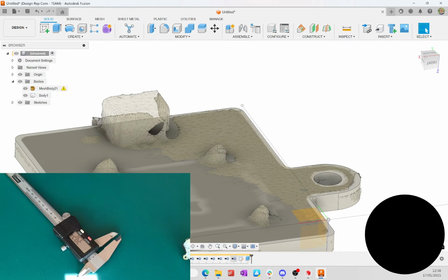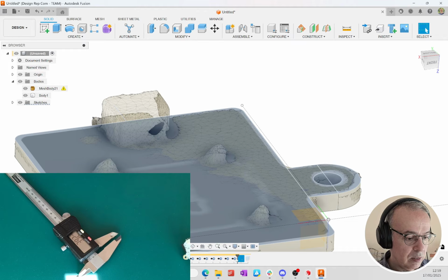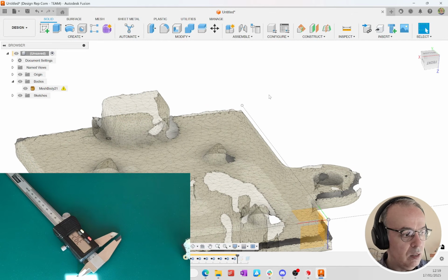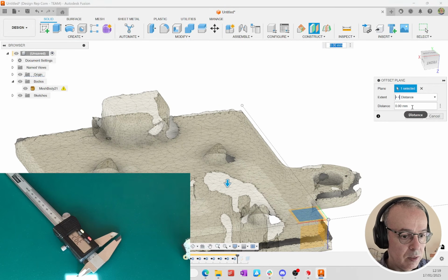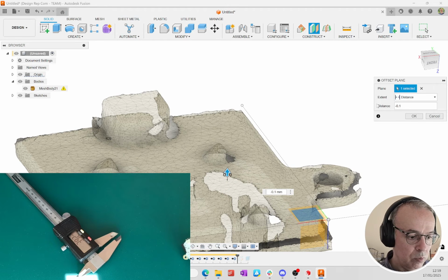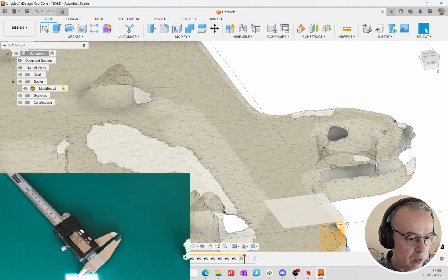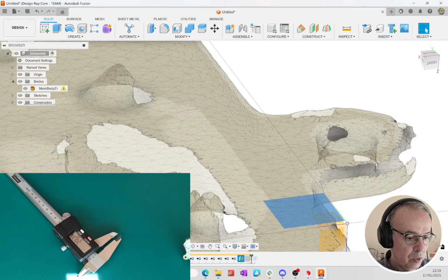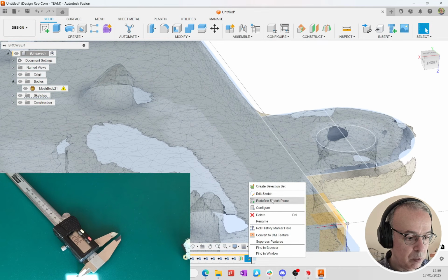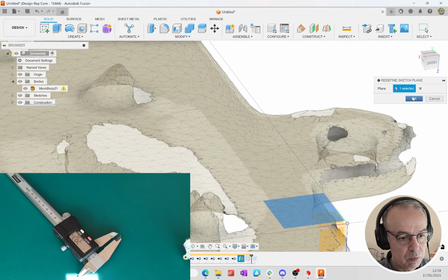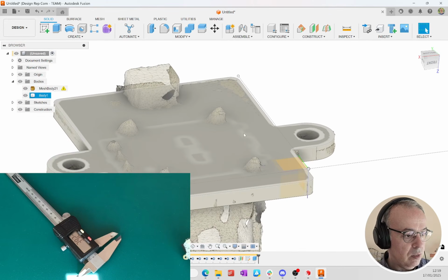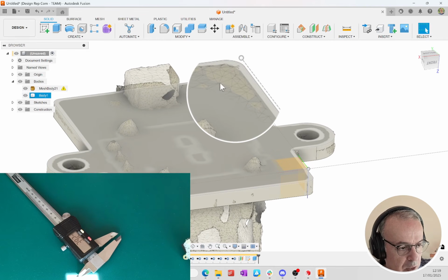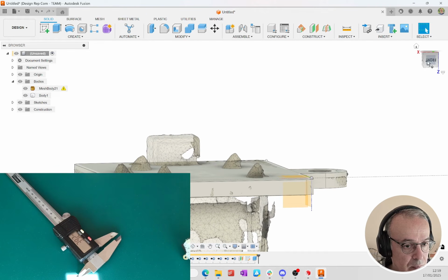To completely resolve the issue, we could add a value of 0.1 millimeters on the opposite direction of the extrude, but we can go back in the timeline to before the sketch creation and create a parallel plane with an offset. A plane was created with an offset of minus 0.1 millimeters, resulting in a new plane positioned correctly. The sketch was transferred to this new plane, which is slightly below the previous one, allowing for greater precision in modeling. The extrusion was reactivated, and it was observed that the coverage was almost complete, except for a small area.